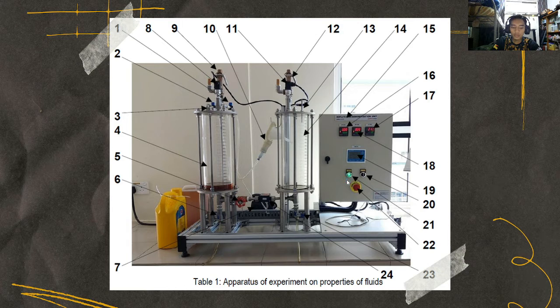And then after that, we will close the valve BV101, number 2, and we will slowly open the valve GV101. The GV101 is number 5, this one, the red one. After we slowly open it, we will take the temperature reading on TT101 and make sure the volume of air did not change. After that, procedure number 7 is to close GV101. We close it, and then when the oil level reaches 214 milliliters,